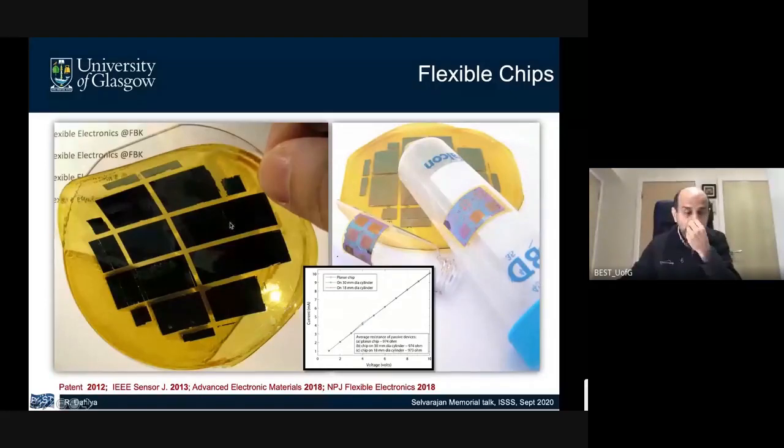This is the dummy silicon wafer with different sizes of chips. And these chips are encapsulated. Bottom is polyimide and top is also polyimide. And the thickness of top and bottom, or substrate and encapsulation, is decided in such a way that the top surface of the chip lies more or less in the neutral plane.